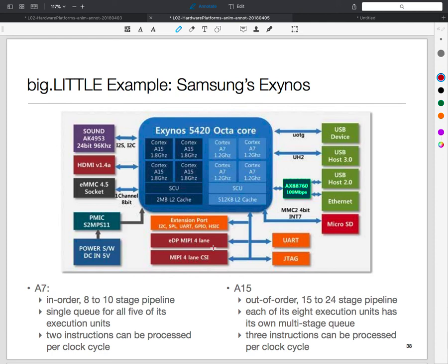The way this particular chip worked, I could not have a little and a big in a given pair simultaneously on. So it had to be a big or a little, but across those 4 clusters I could make any given choices. So I could have like 2 big, 2 little on, and things like that. So I could do that scaling also out here.